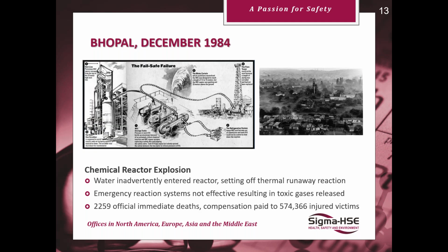The next one was a horrible disaster in Bhopal in India, 1984. They had a storage tank of methyl isocyanate, which had had issues pressurizing the nitrogen head because it needed to be inert. Various issues meant that this storage vessel failed and a thermal runaway reaction was initiated. They think that some water entered one of the lines and triggered the reaction.